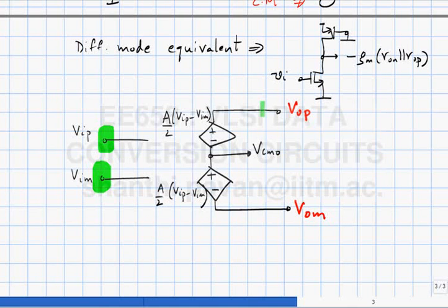If you put 25 millivolts into a voltage controlled voltage source with a gain of 1000, you will get 25 volts, and that is clearly outside the range over which this op-amp is operating, with switches and capacitors and all this stuff. The switches are all MOS transistors. Those models are only valid when the supply voltage ranges from 0 to 1.8 volts or 2 volts or something. The moment you exceed these supplies, the models will go crazy and the simulator will complain like mad.